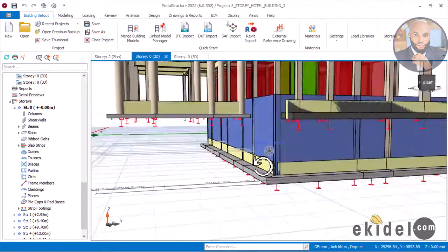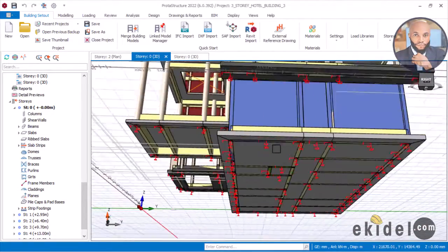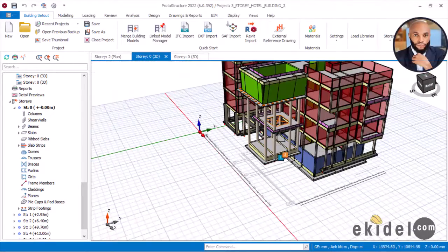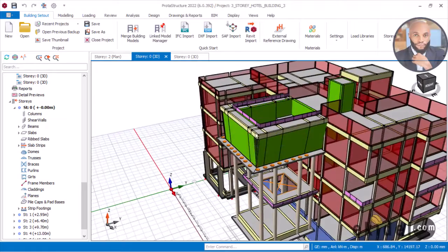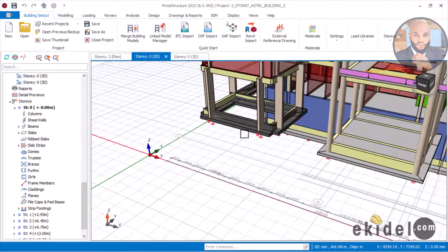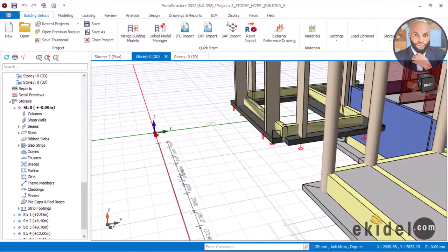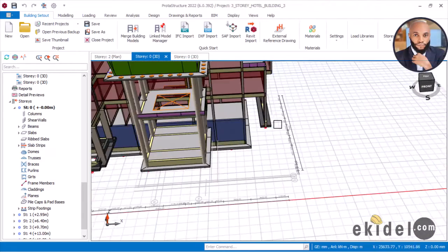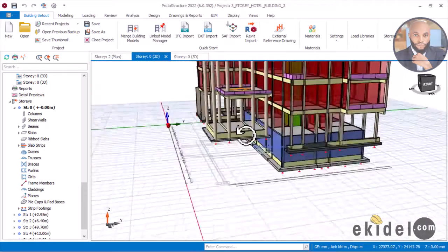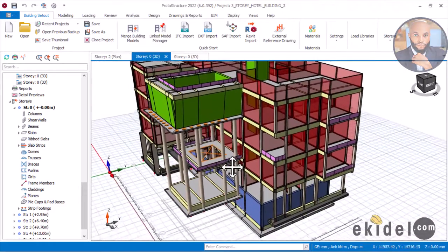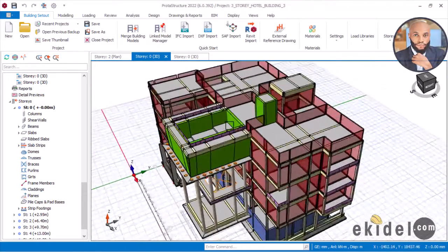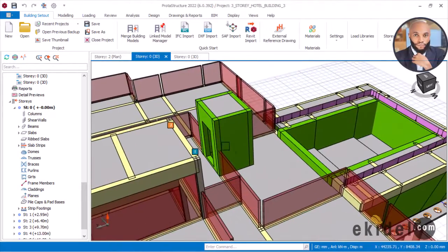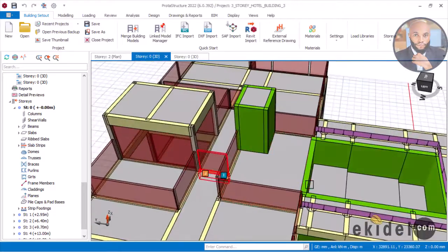We use this one as a raft foundation, which is a slab raft, and this other part only a beam raft, which is carrying this pool here at the top. On all other places on this other side we use a strip foundation, and on this other side too, we also used a strip. So we'll have several foundation designs for this building in particular. You can also see the top here and the lift going up, and how the pool is being modeled and designed.